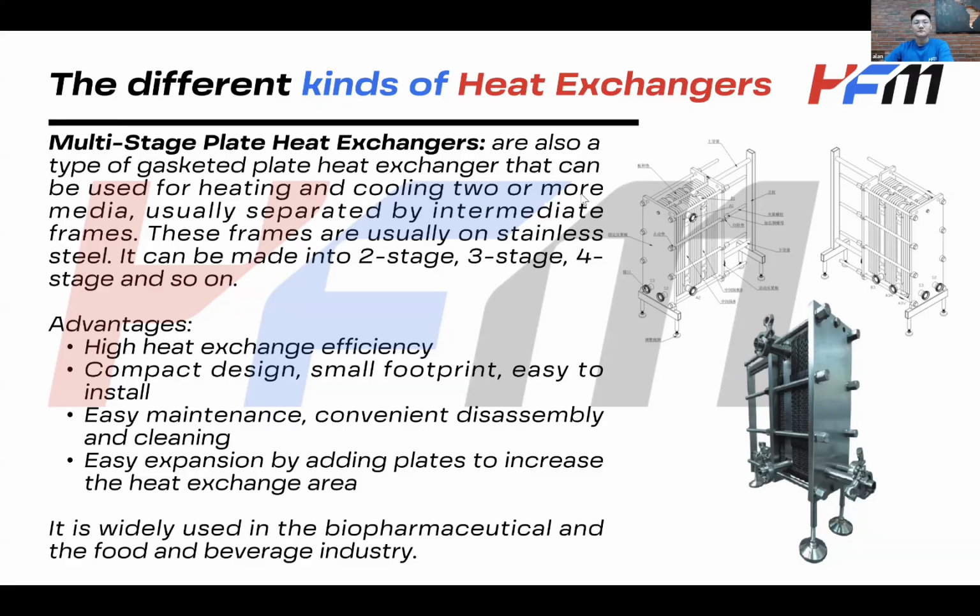I think it is 45 bar G with a temperature limit of 225 for the brazed heat exchanger. And for the other kinds of exchangers, all of them should be under 30 bar G with a limit of 200 degrees.